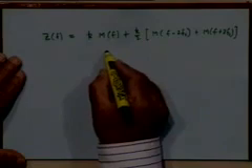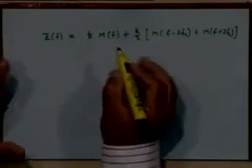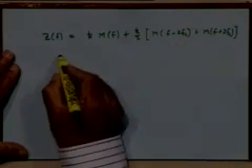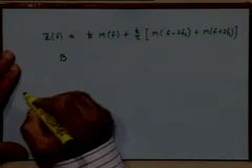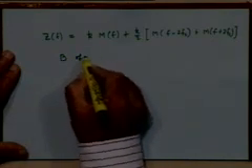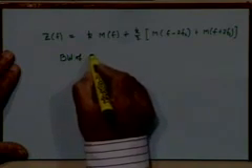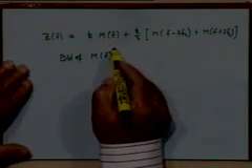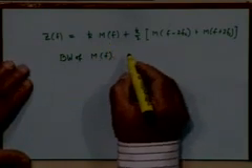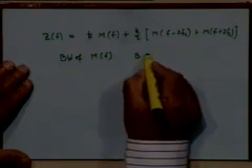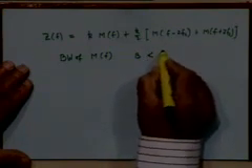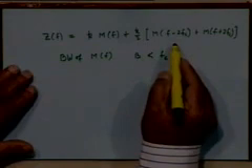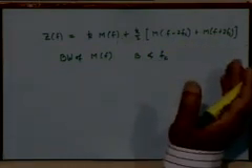And as we know, if fc is suitably chosen, what is the requirement? That the bandwidth B of M of f, the largest frequency component in m of t, satisfies the condition that B is less than fc. Then obviously it will be also less than 2fc, and these two spectra would not overlap.